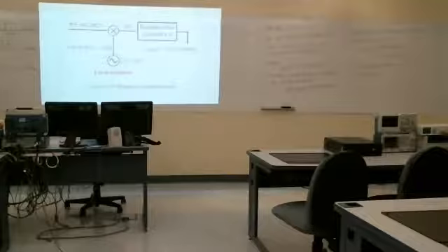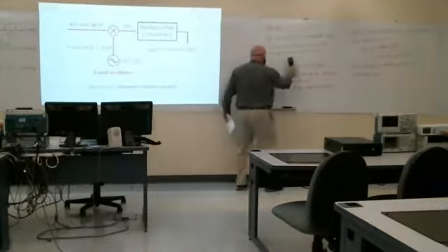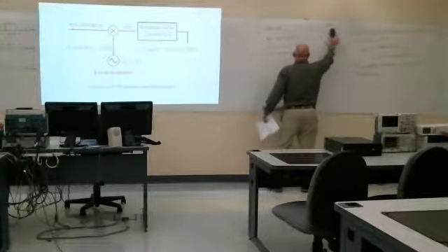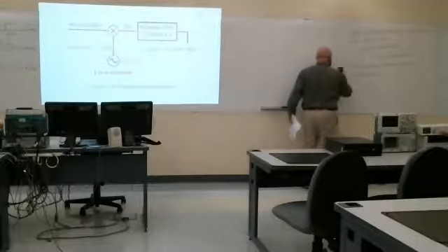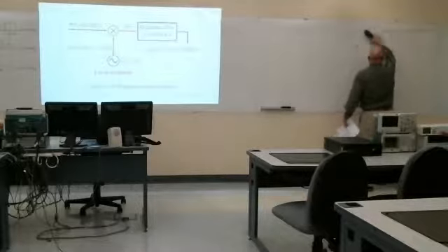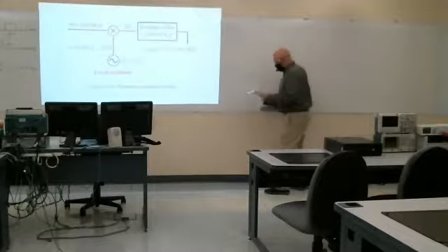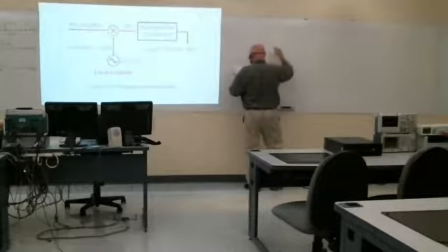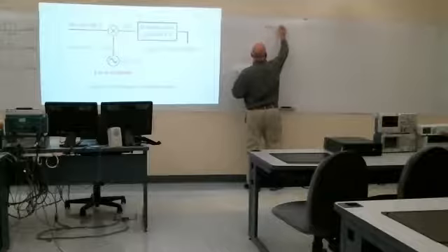Okay. Modern receivers actually use a tunable oscillator instead of a tunable bandpass filter. It's actually a lot easier to build a tunable oscillator than it is a tunable bandpass filter. And I'll draw the picture here.